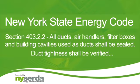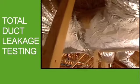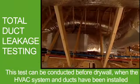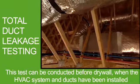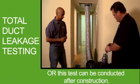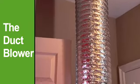There are several duct leakage tests that can be used. The one we'll look at here measures total duct leakage. This test can be performed before drywall, when the HVAC equipment and all the ducts have been installed, or it can be performed after construction, which is what we'll show. The principal tool for verifying duct tightness is the duct blower.